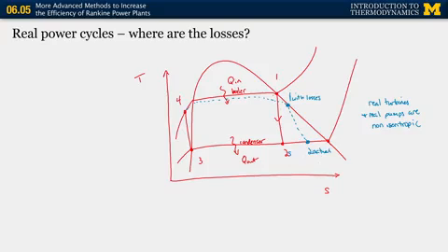And what we would do is compare the device performance. We will circle back to this, but it's going to take us a little bit of time to get there. We talked about ideal cycle performance and how we use the Carnot cycle to define that. Device performance is also defined by the second law, as we mentioned a couple of segments ago. And what we would do is compare the work out of these two processes, the isentropic process and then the actual process. And we would define that as the device efficiency.